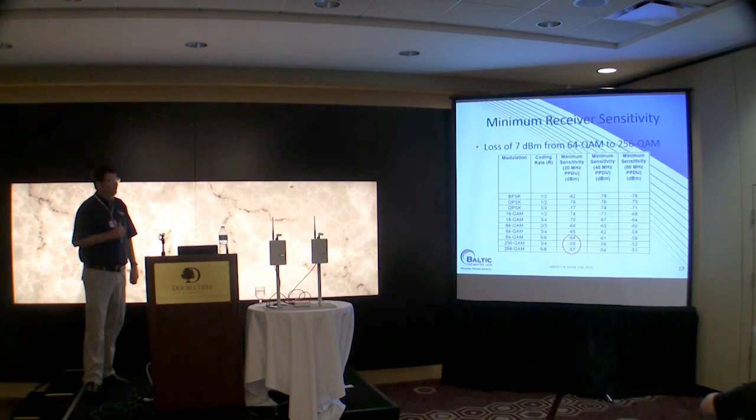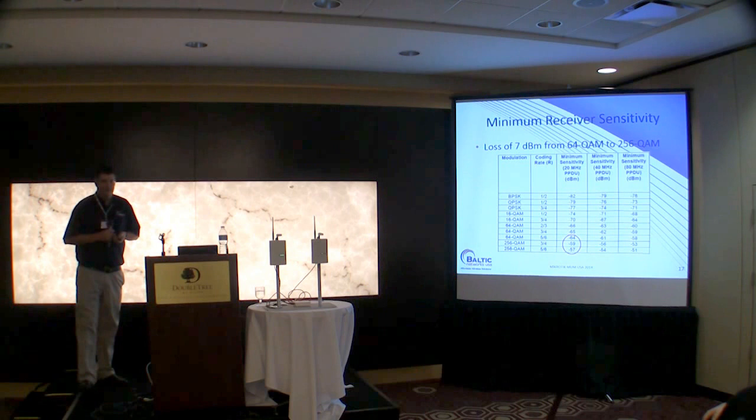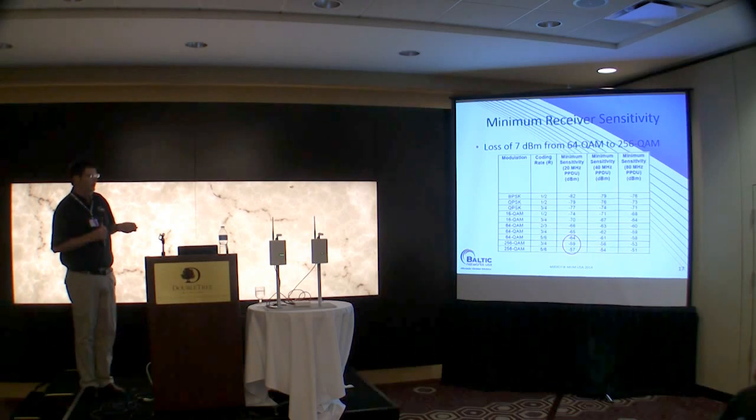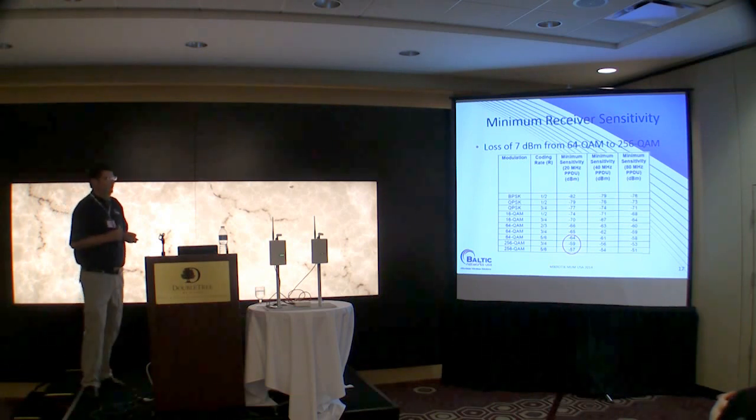So to the specs, the receiver sensitivity changes from 802.11n to AC. With 64 QAM, you'll see we had a negative 64. And again, these are specs. These aren't RouterBoard specs. These are just the AC specs. With 256 QAM at full modulation, we go from 64 to 57. And that's a 20 megahertz channel. So you'll see that means we need a higher power to run these types of higher modulation rates.